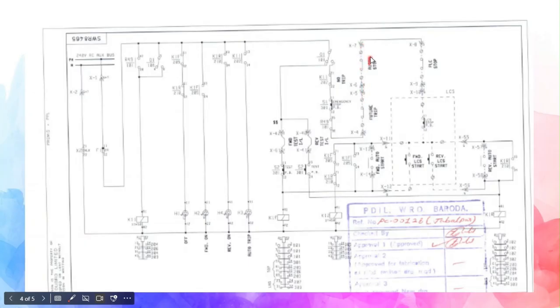Auto stop. This is a command from the PLC. In process plants, sometimes these motors are run automatically using a process model. So this is an input from the process model, which will indicate that it is tripped depending on different other signals in the PLC itself. I mean, this signal is generated by the PLC automatically. But look at this signal, PLC stop: it is generated manually by somebody from the control room. So this is the difference between these two signals.